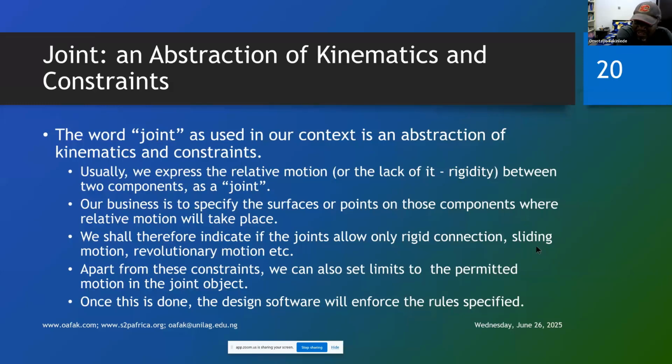If you are using general joints, it is your duty to specify and make sure that the center of the rotation you want coincides from one to the other, because if not, the general joint will force that to happen, and in doing so, it may move one of your components. Many times when you are having difficulty, that's what is happening. You probably have specified the surface, but you have not specified the center of motion correctly, and Fusion 360 is not understanding you, and it thinks it needs to move one body to get to the other so that the centers are located in the same place.